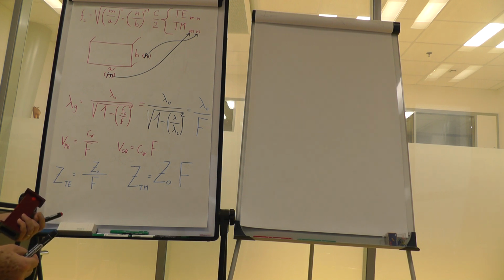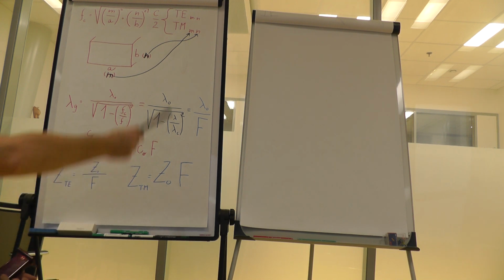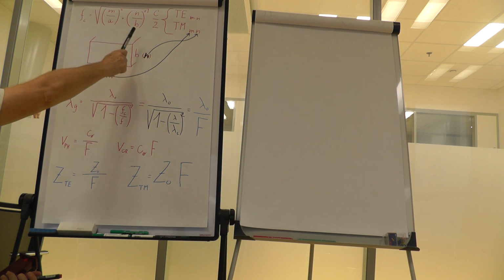So if we now can name the modes, we are also very interested in one important equation, which tells you the minimum frequency at which this mode could propagate between those metallic walls. This is called critical frequency, and the equation for that frequency is just here.